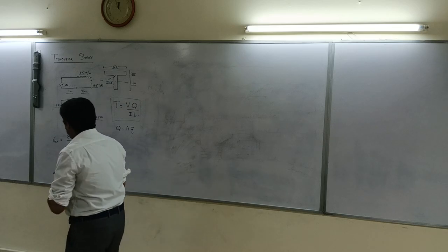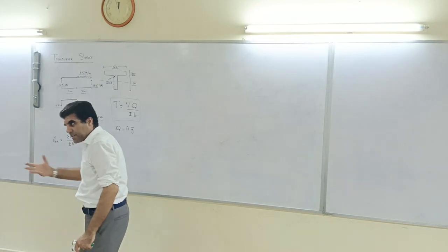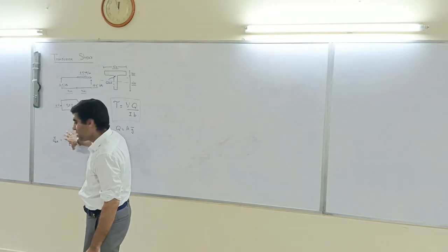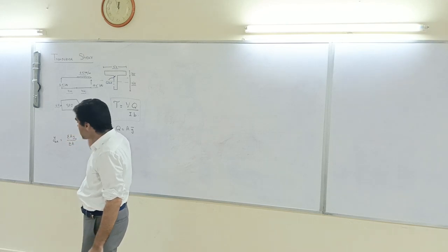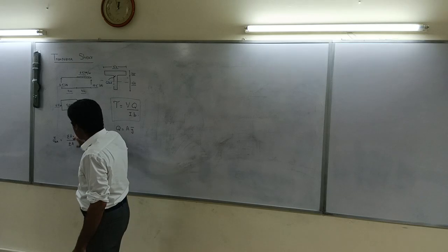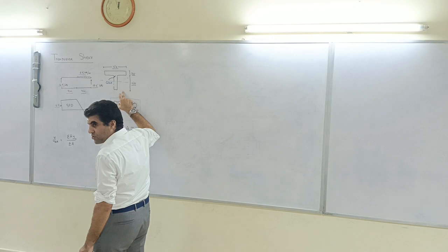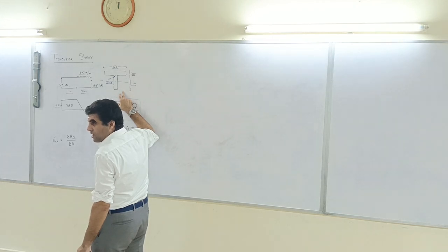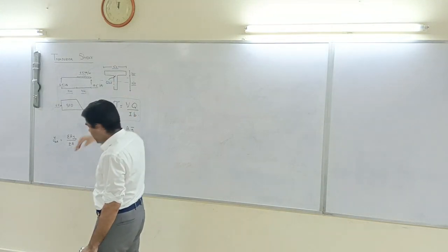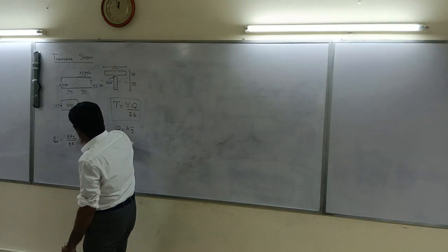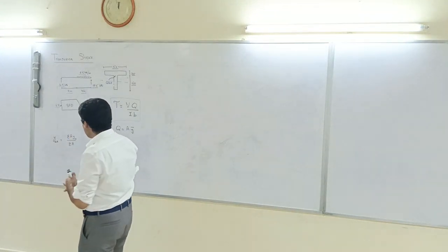You have done that, this is the centroid formula. The neutral axis formula, you are trying to find out the neutral axis. And how do we do that? You take a reference point and, corresponding to that point, you find out area moments. So divide it into pieces, find the area moments divided by the total area and you will get your neutral axis.